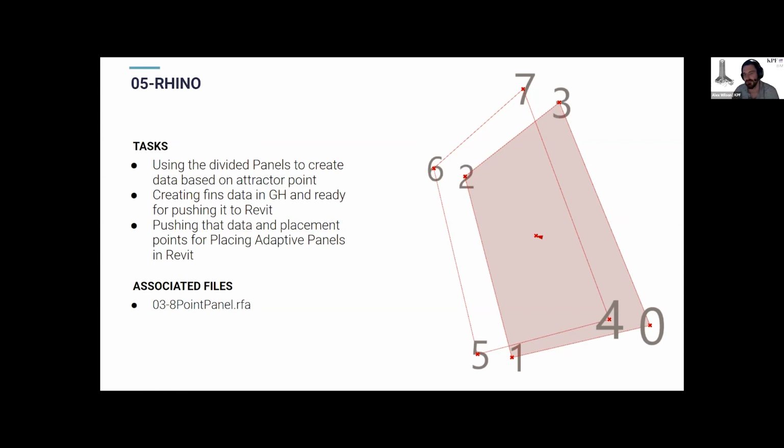had to add that additional line and then recreate the chains to create the profile sweeps around the outside. As it added complexity, what we ended up doing was building an additional family and loading it in. It was just a 4-point family that had an extrusion within it, which allowed us to then just click the points and place them in the adaptive family.